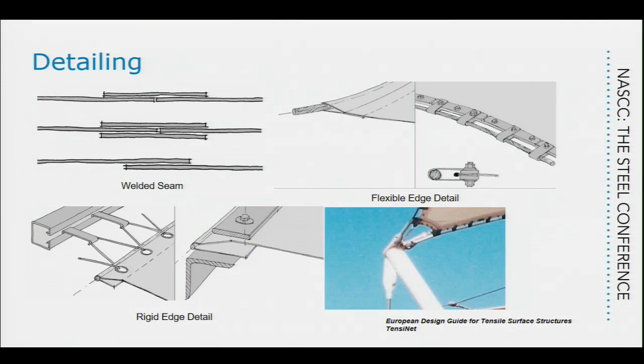How much force is going through that connection determines how much we overlap. In your patterning, you're going to have this offset of the strip so that you can overlap it. And if you were very tight on your rolls, all of a sudden you don't have enough material to achieve the overlap.